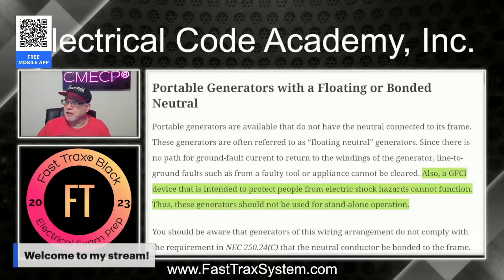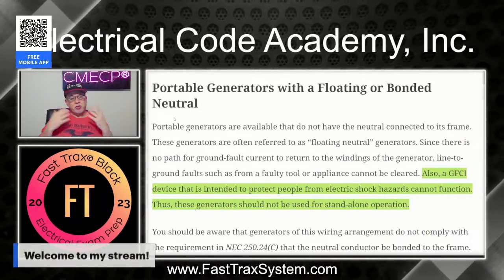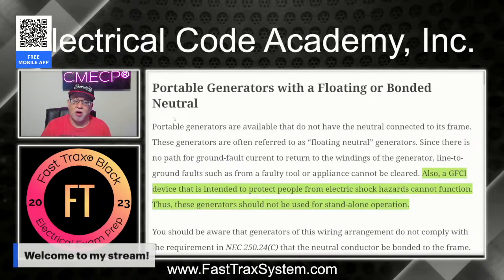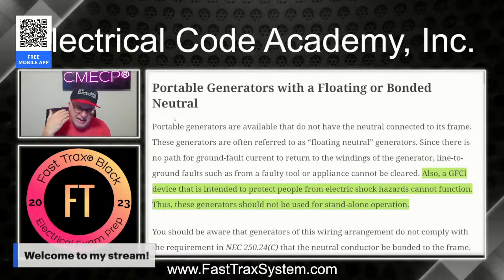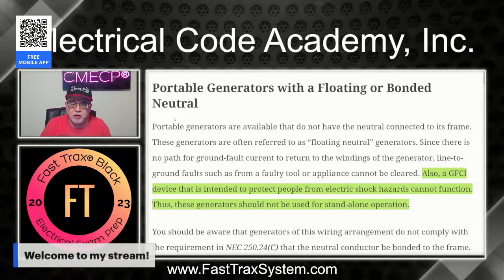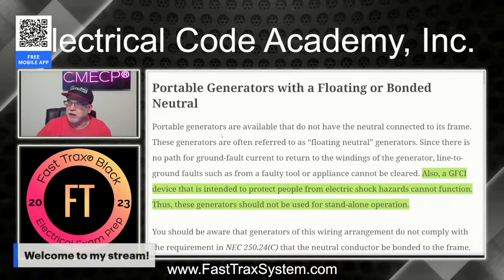Let's dig a little deeper here. I've got an important area highlighted for you. Portable generators: there are two different types you're going to run into. You're going to get some that are the bonded neutral, like what we just saw, and then you're going to get a floating neutral. The bonded neutral meets the rules, and it's going to allow the overcurrent devices on the generator to trip. It's going to allow the GFCIs to function properly, whereas on a floating neutral, that just can't happen. That doesn't mean that you're not going to overload and trip an overcurrent device, but I'm going to show you how it really can happen when it comes to the floating neutral.